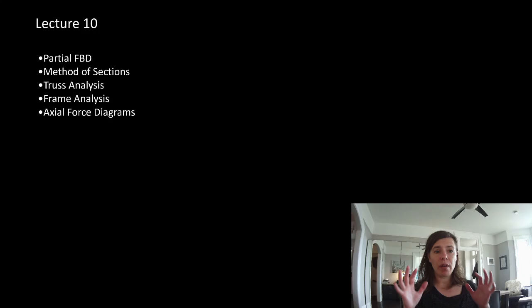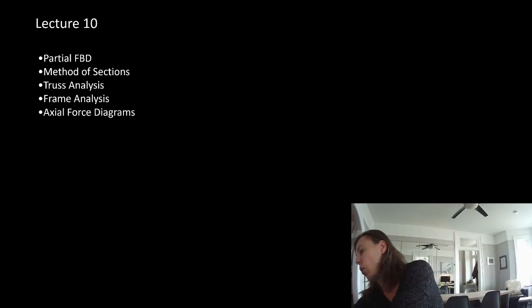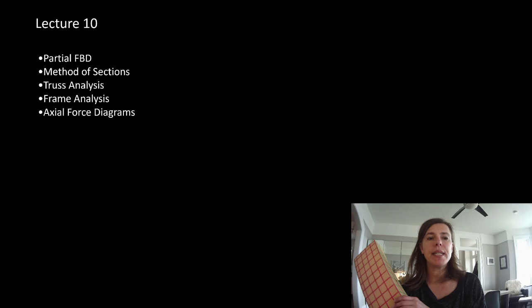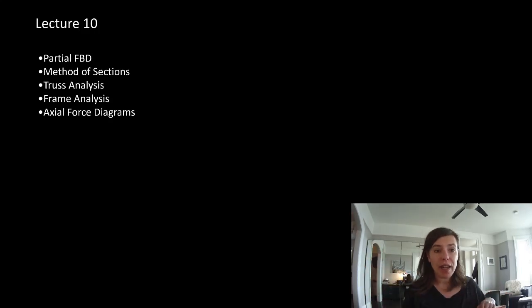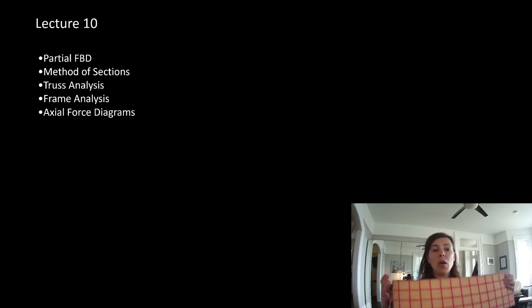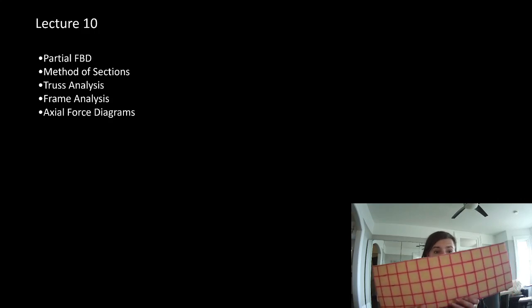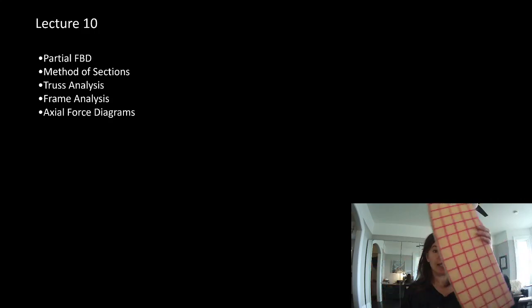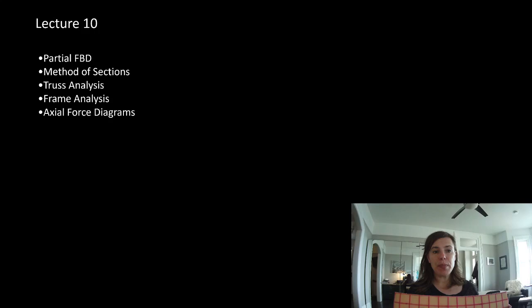Now, up until now, we figured out that we could figure out all the loads on a building or an object, and we know we can narrow it down and find the specific kind of smaller loads that act on an object. We now know that we can use summing the forces in the y direction, the x direction, and spinning about z, needing to be 0 to ensure it's in static equilibrium, to figure out what reactions are required to make that true.